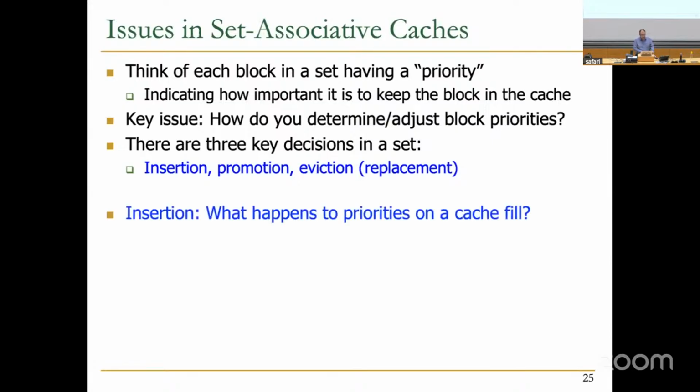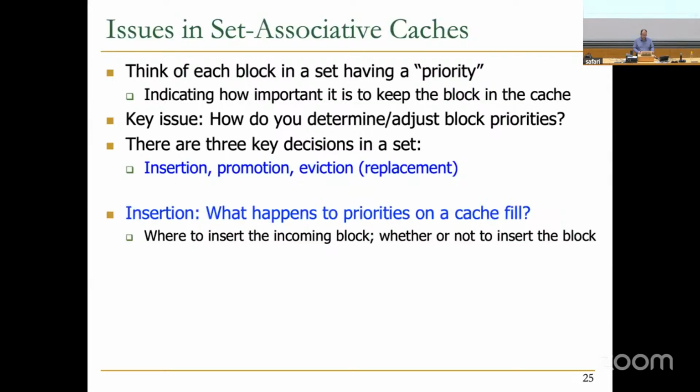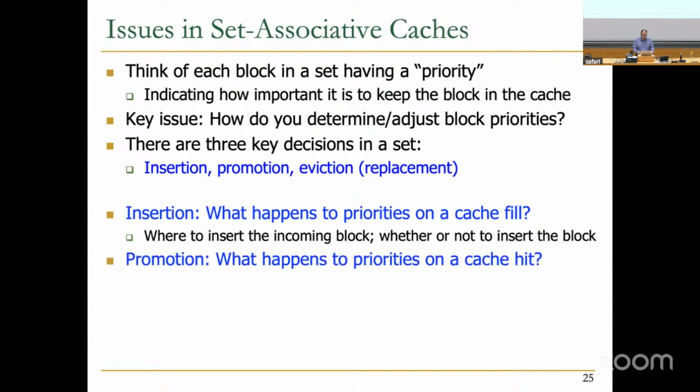Insertion is basically what happens to priorities on a cache fill. When you insert a cache block into your cache, how are the priorities going to change? Where to insert the incoming block, or whether or not to insert the block. Actually, sometimes you decide not to insert the block, and we're going to see that later on. So that's a decision you need to make.